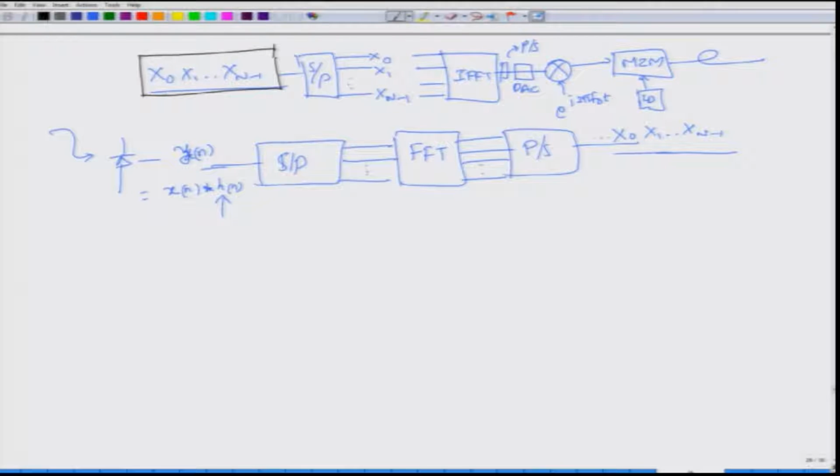These are usually arriving serially at the transmitter side, and these bits, generated serially either from a source or from a computer, are then converted into parallel form using a serial to parallel converter. So, you have a 1 to n converter over here, which puts the n symbols into parallel form. Once you have the symbols in parallel form, the symbols are the data at this point. These complex data are then passed through an IFFT, that is, we take an inverse Fourier transform, and after the inverse Fourier transform we convert them again back into serial data format. So, what you get after the parallel to serial conversion is again the IFFT samples, the sequence of samples x of n, where n goes from 0 to n minus 1.